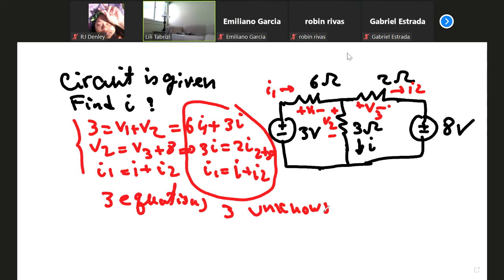And the reason is you have 3 unknown currents because you are applying current voltage pairs to each passive element, and you have 3 passive elements. So you eventually need 3 equations. You are perfectly fine. You can write the outer loop. But then you have 1 outer loop, 1 inner loop, 2 equations, and 1 KCL. This is the exact method. KVL, KCL, Ohm's law. Any question?